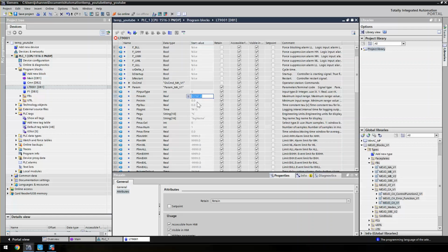Anyway, we're using 0 to around 12,000 since we're reading 0 to 5 volts, and our input cards and output cards are plus minus 10 volts. So we'll be using half and then calibrate the rest. Somewhere around this number is correct for 5 volts.